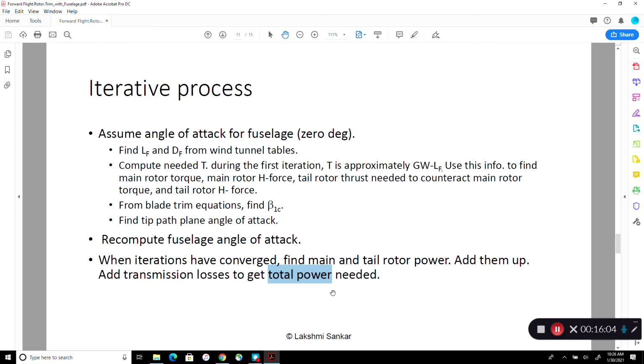So what happens is you are producing the blade rotation to maintain its RPM. But the actual power that you need is coming from your potential energy. We don't want to lose the kinetic energy in the rotor, so when the rotor is spinning, you're losing altitude. So the rate of descent is important. How rapidly am I descending at a given forward speed? You want to know when you're going to hit the terra firma, when am I going to hit the ground. So we want to know what's going on.